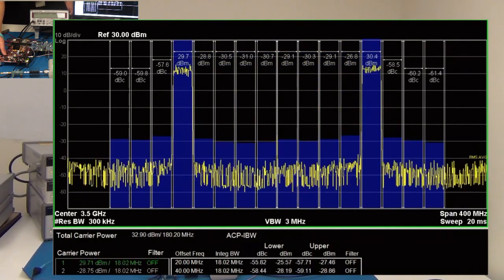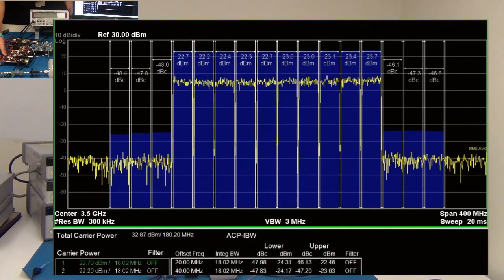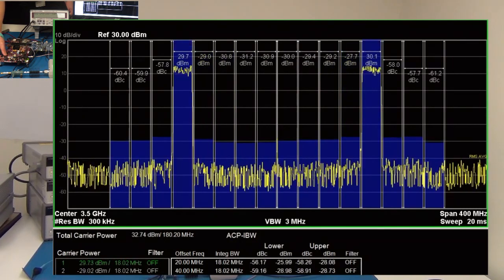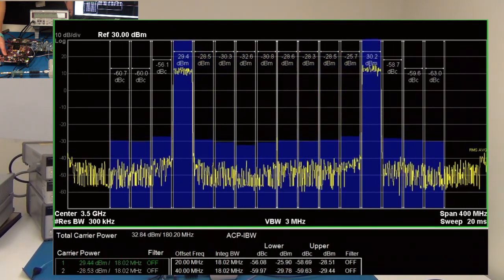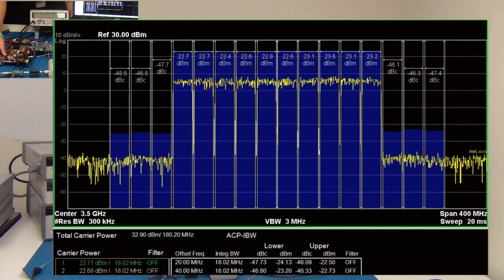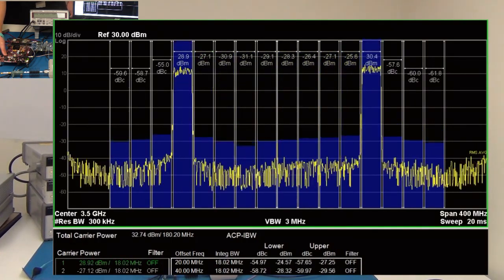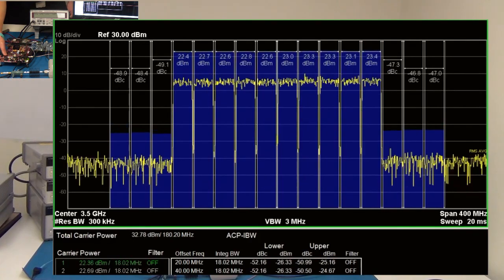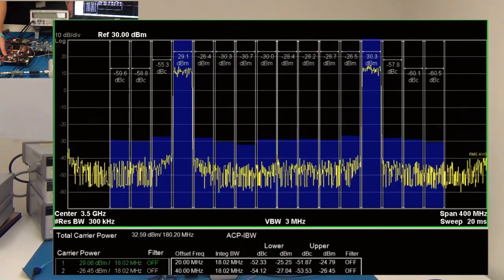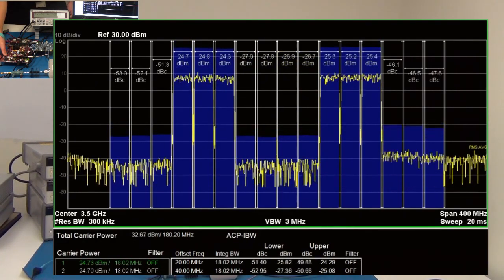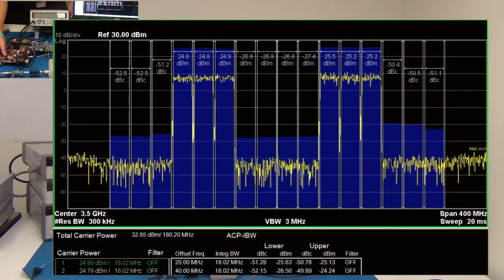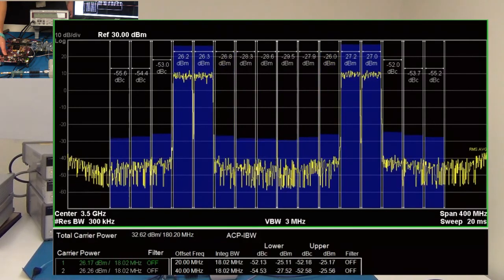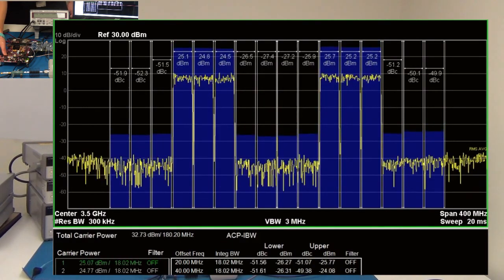By looping through these different carrier configurations rapidly, we can show that there is no disruption in RF spectrum. And we can more or less maintain 50 dBc or better linearity for various 200 MHz test cases, while operating the power amplifier at 2 watts RMS.